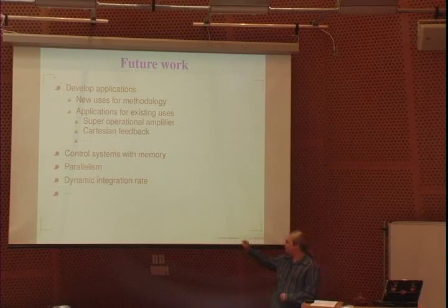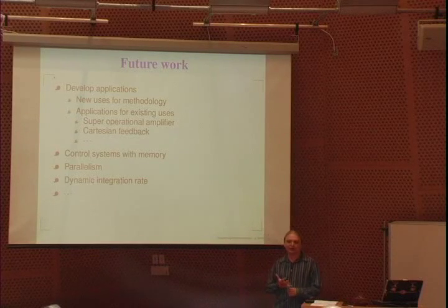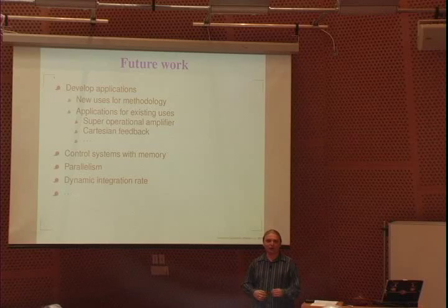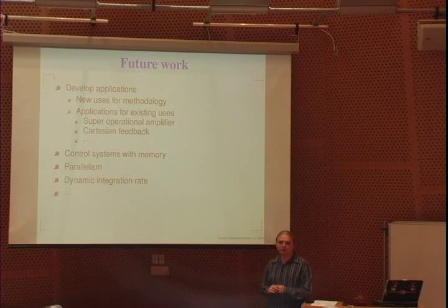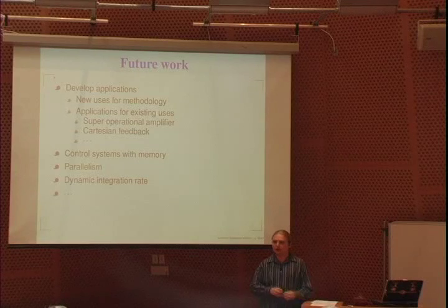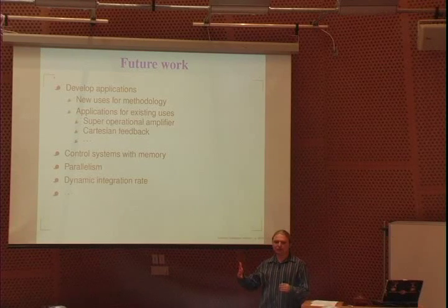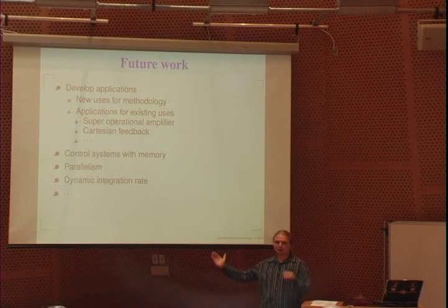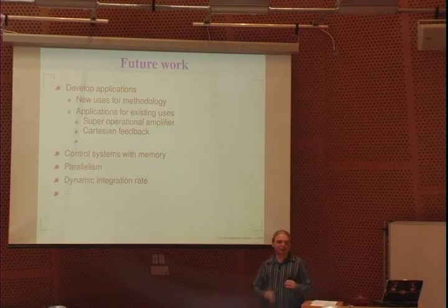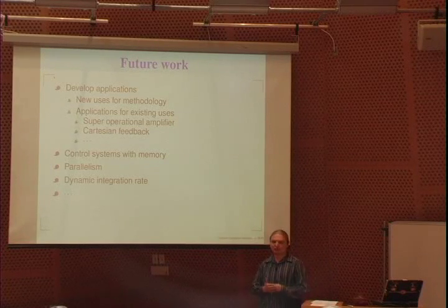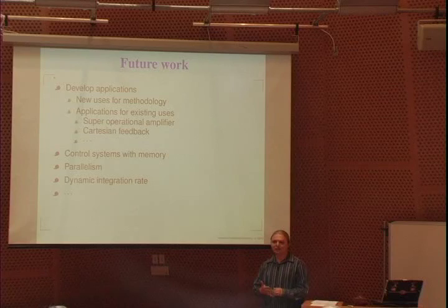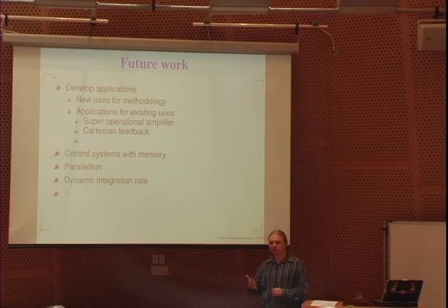One example of this is called Cartesian feedback, a technique that's used for RF amplifiers. In Cartesian feedback, you take the signal, you modulate it, you run it through an output stage, you demodulate it, and you feed back to make sure that the output signal tracks the desired input signal. The feedback loop there is hard, and there are people like, for example, Joel Dawson at MIT working on building various types of models of a system like that, so that you calibrate this once, you figure out what input you need to have to give a given output,